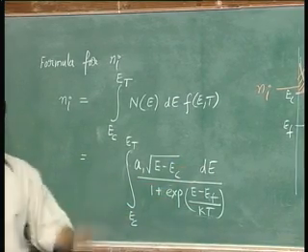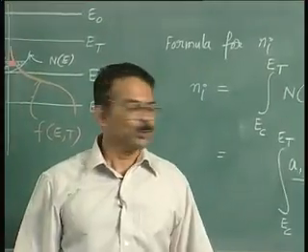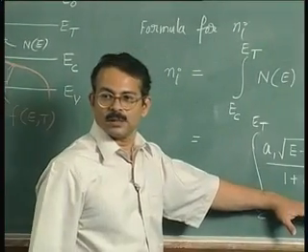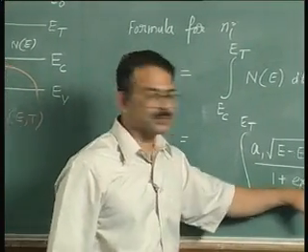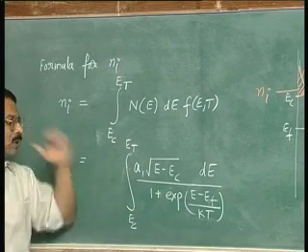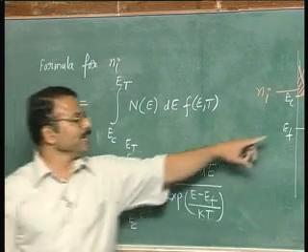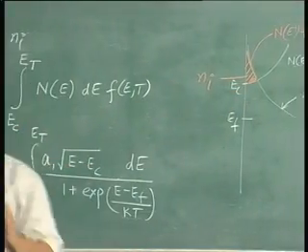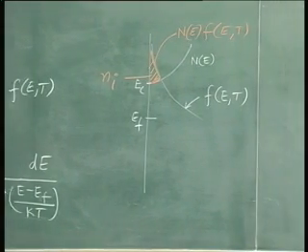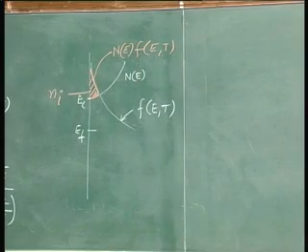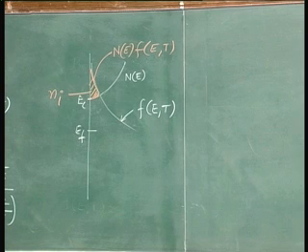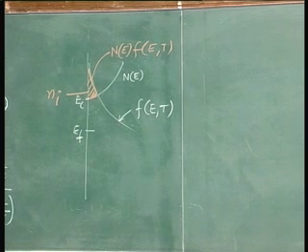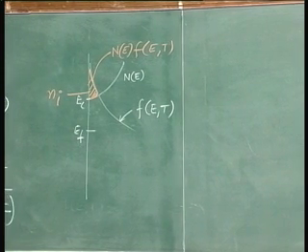So one uses some approximations. So first thing is the Boltzmann approximation. You use the Boltzmann approximation to this Fermi Dirac function, because one can show that your EF will be below EC by more than 3 times KT. Now you do not know this in advance, okay? But from intuitive reasoning one can know this.